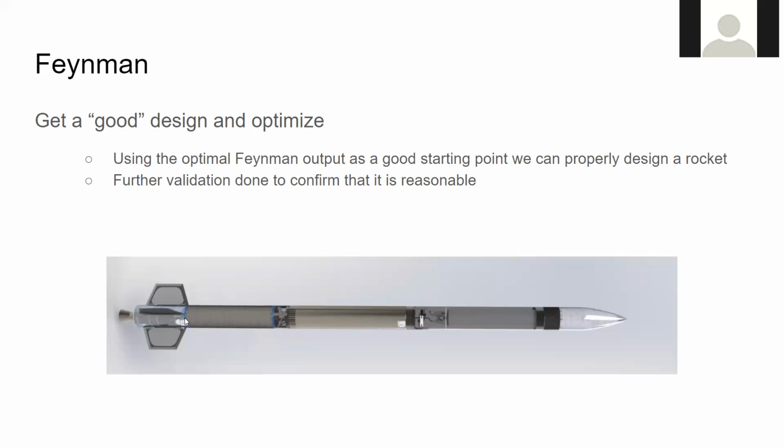And then our engine is made of a combination of mild steel, aluminum, and stainless steel. Our fins are a milled aluminum frame, and then we stick a low density foam on the inside so that they're still quite strong, with a lot of resistance to compression. Then we put carbon fiber over the edges to give it an aerodynamic covering.